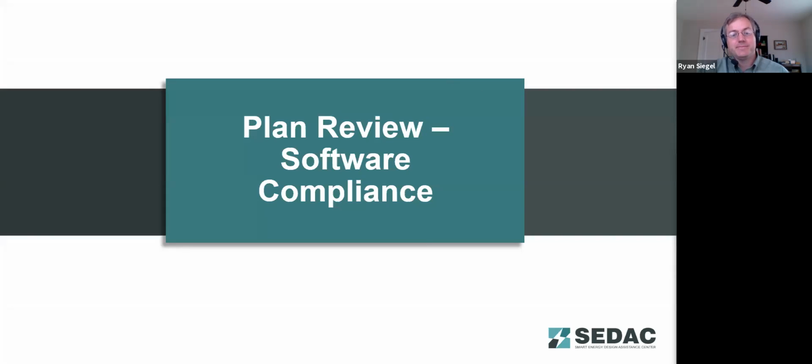We did have one more question come in through the chat that I caught. Do we need an air barrier for ICF walls? ICF walls typically are the air barrier themselves, because the concrete typically is the air barrier.